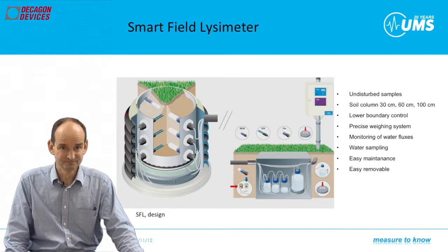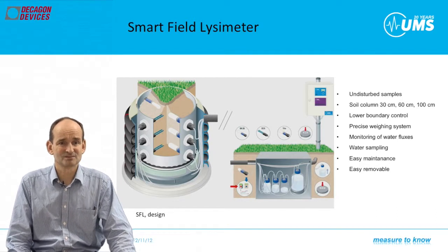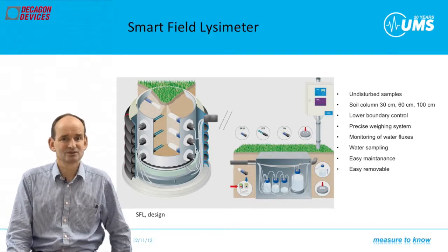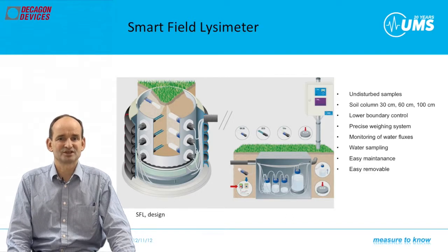meters away. The 10-liter drainage reservoir tank stands on another precision platform balance and has a siphon which empties the tank at the level of above 10 liters down to 8 liters automatically. The 8 liters remain as a reservoir for the dry seasons to keep the lysimeter moisture equal to field conditions. Also, a 5% sample bottle is filled each time the pump takes off drainage water from the lysimeter for analyzing issues of the drainage water. The provided overflow gets into the drainage tank.